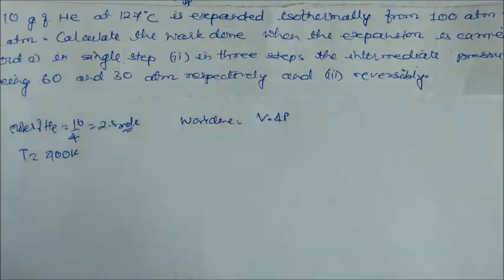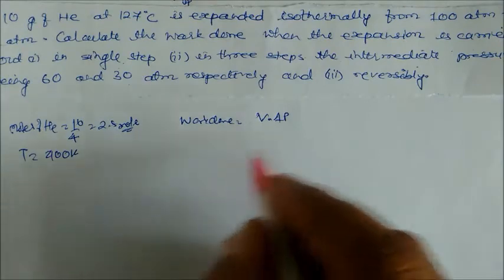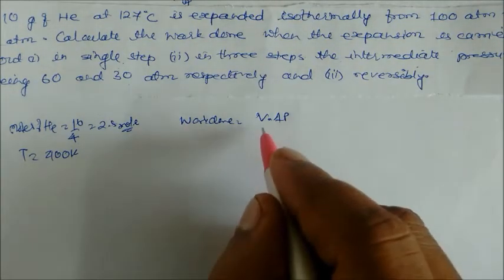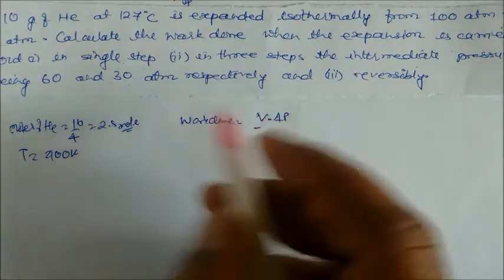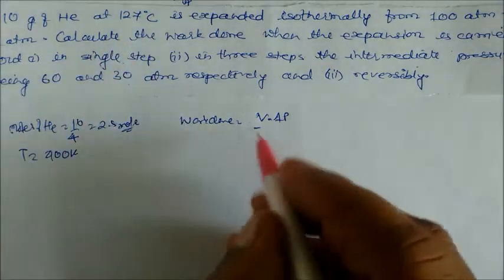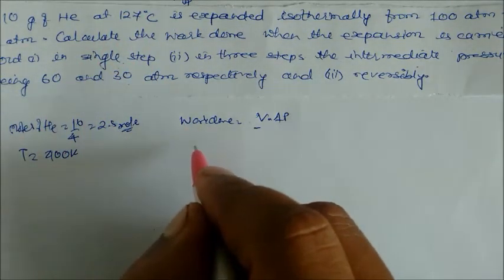This is the work done. For the single step we have to find out. So here first we have to know how much volume is given, because volume is not given in this question. So we have to find the volume first. So use the ideal gas equation.